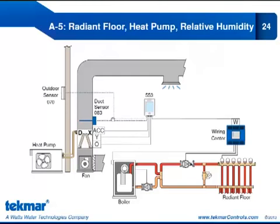The duct sensor 083 is optional in this case to provide freeze protection for the coil. Notice there is no G relay in operation because we're using the GO relay for the reversing valve. So in this case, the air handler unit is going to operate the fan whenever it receives a call from Y or the accessory. When it is in heat pump cooling, it would operate the fan probably at a higher speed. When we're doing dehumidification, the fan would operate at the dehumidification speed, which would be a lower speed.